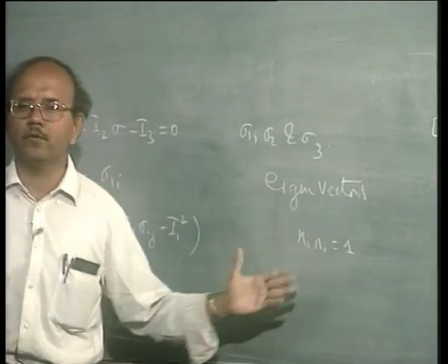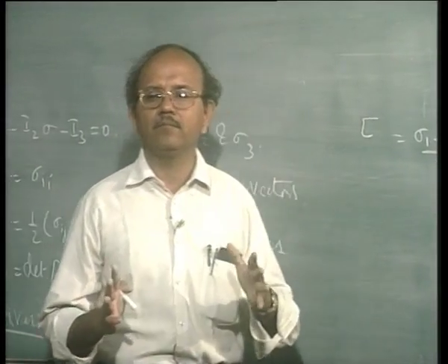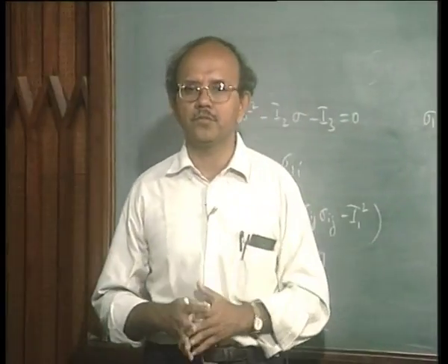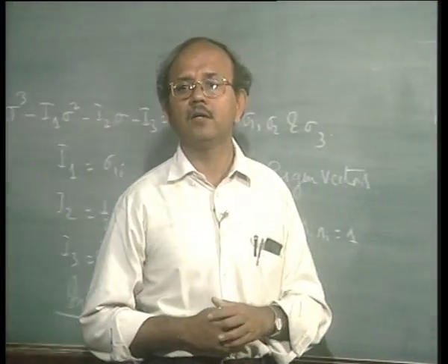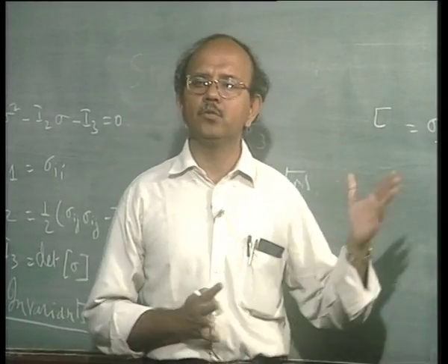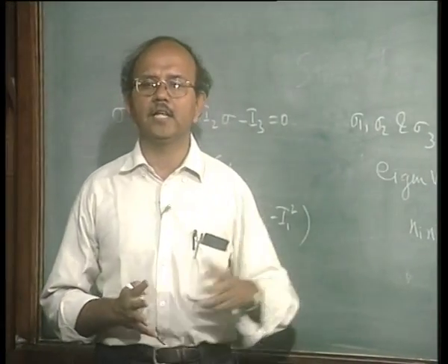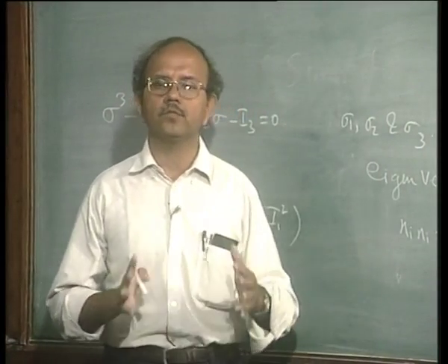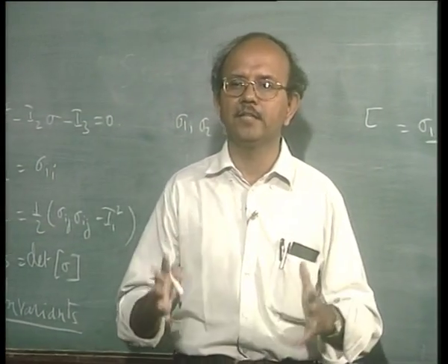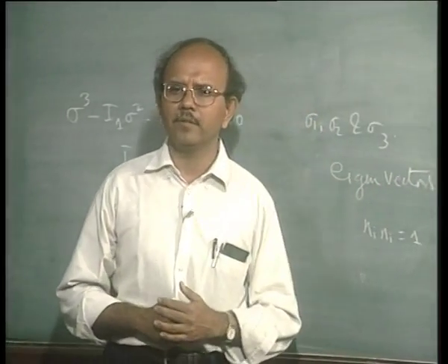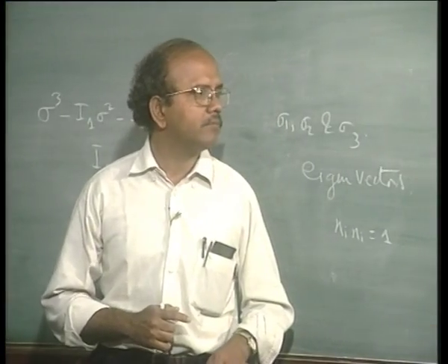In other words, whatever we saw just now, principal stresses can be arrived at very naturally from our definition of stress, and are quite useful if you are going to use Tresca's theory or, for certain brittle materials, the maximum stress theory, where the maximum stress signifies failure. I am sure all of you have studied this in your design courses, so I am not going to repeat that. On the other hand, let us go to what is called Mises theory.